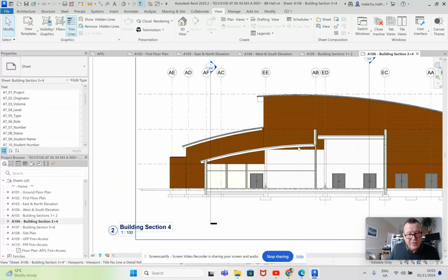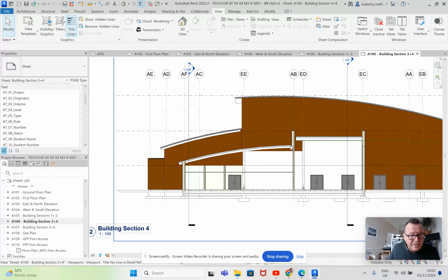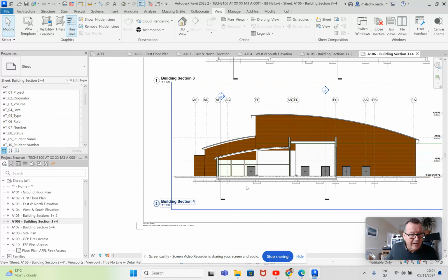Now you could kind of curve the walls, okay, so you could bring this one up and curve it, and then you could curve the external to sit down on top of it. Whether that's worth doing or not, that's entirely up to you. Would you do that in a real project? I don't think so, to be honest with you. What you want to do is get a good seal on the roof here. That's the important bit, is to be able to get a flashing and counter flashing seal on in there.